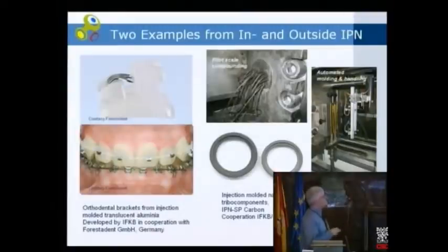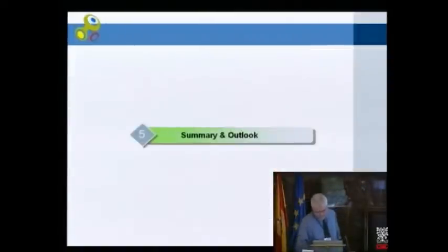the sintered component. And the interesting thing in these nanostructured carbon components is that you can produce such seals in a very high quality. The bending strength of such a material is in the range of the best fine-grained graphite you can buy at the market, and it has a near net shape processing capability, but we think that there is still some room to improve this.